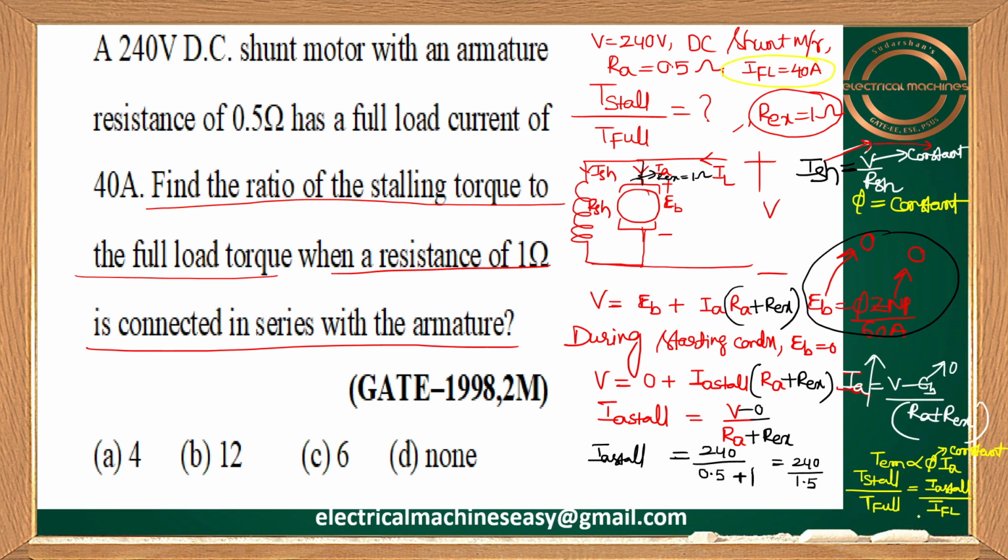So please tell me, I_stall by I_FL means, I can write here, I_stall value how much? Otherwise I'll give a remark and I'll write here only. Yes, please tell me I_stall value how much? So 240 by how much? 240 by 1.5 is the value. Okay.